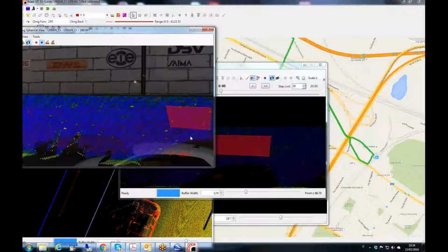So if you need to draw a hatch on a wall of a house, you can select the correct hatch you need in your AutoCAD project, select the correct layer, and pick points in the plugin, pick points on these windows, and the result is that you have your hatch in AutoCAD.